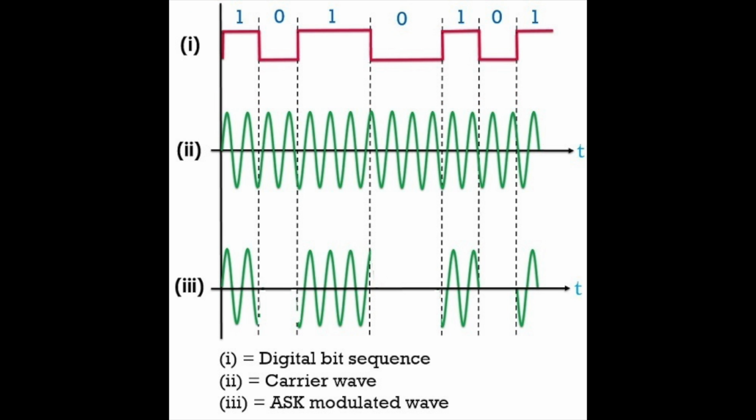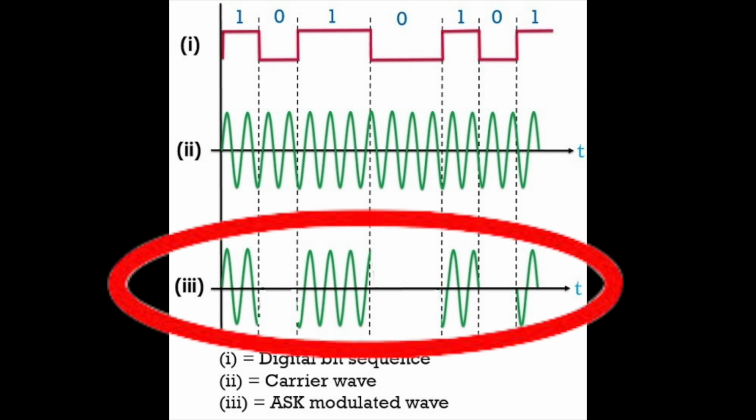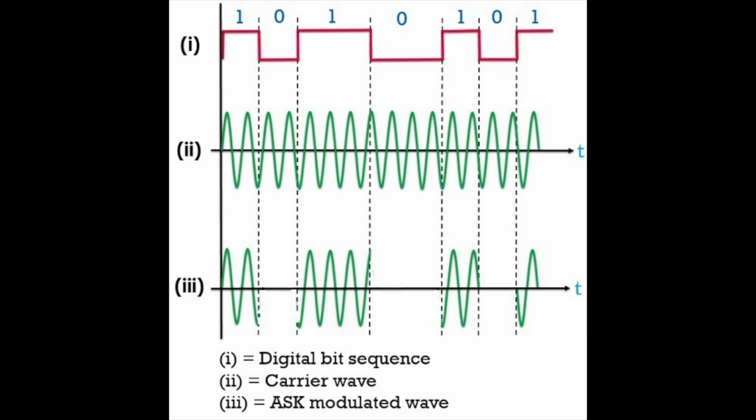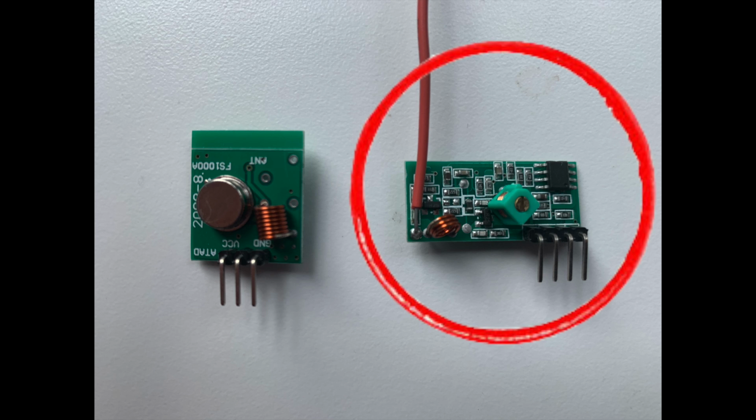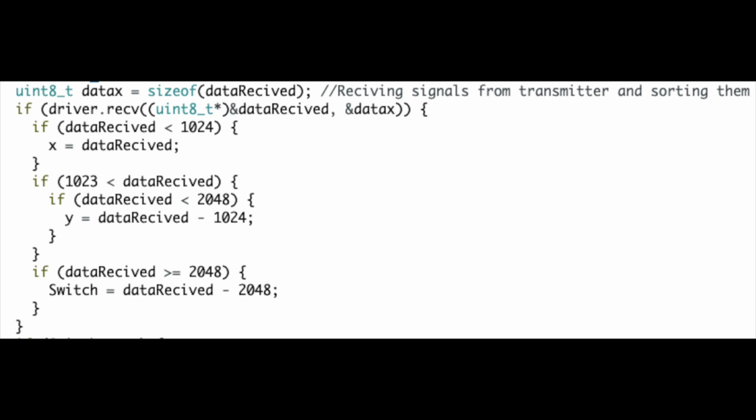This task occurs using ASK, or better known as amplitude shift keying, which essentially forms these waves into 2 different states, the lower amplitude being 0 or a higher amplitude, better known as 1. These waves are then caught by the receiver, in my case the antenna, and then decoded back into letters and numbers.